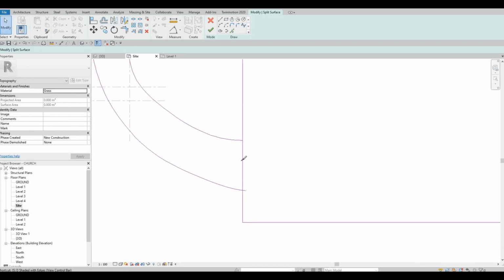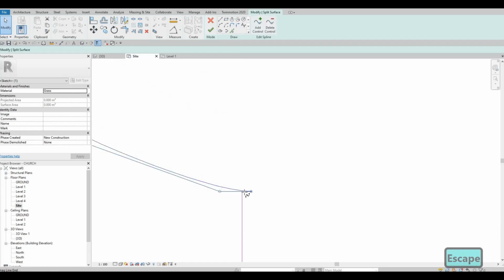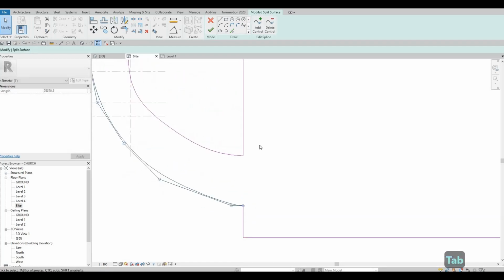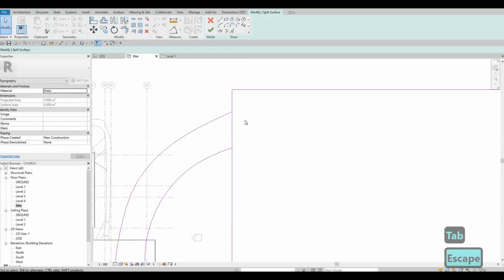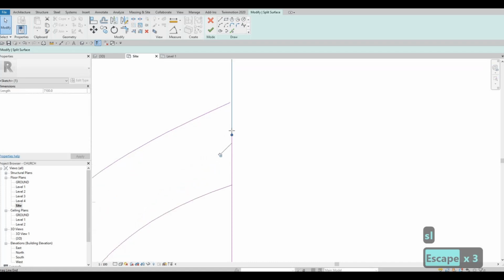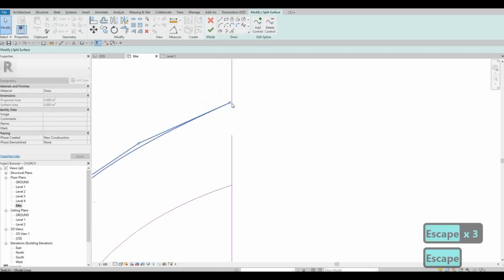And then here SL, that's split element, and then just pull it out and connect it. Try to connect it. This one, I'm just gonna connect it. So I'm using tab just to connect them. SL again to split this, and then grab it and then pull it there.